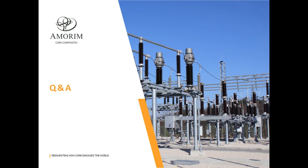Well, the next question we have is if the thickness of the pads is proportional to the equipment weight. The answer is no, it's not. As you saw in the last simulation we did, changing the thickness will change the performance of the material. Increasing the thickness will increase the performance, the isolation value of the material, but it is not related to the weight. We can use higher thicknesses in high weight transformers or low weight transformers.